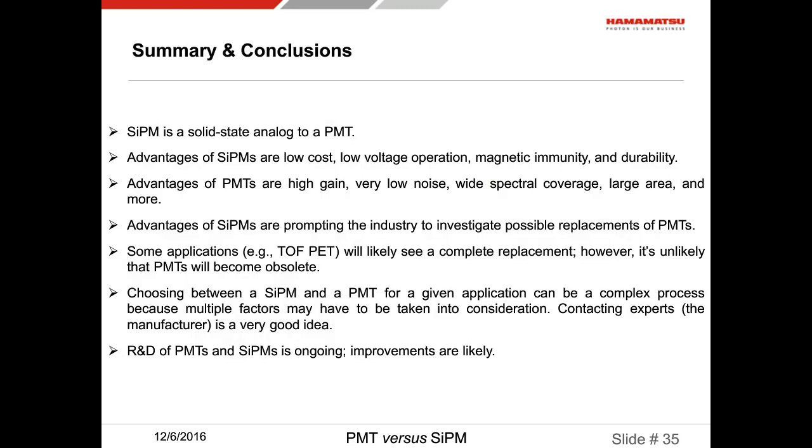We've reached summary and conclusions. I would like to just point out a couple from the list. One is that advantages of SiPMs are low cost, low voltage operation, magnetic immunity, and durability. Advantages of PMTs are high gain, very low noise, wide spectral coverage, large area, and more.